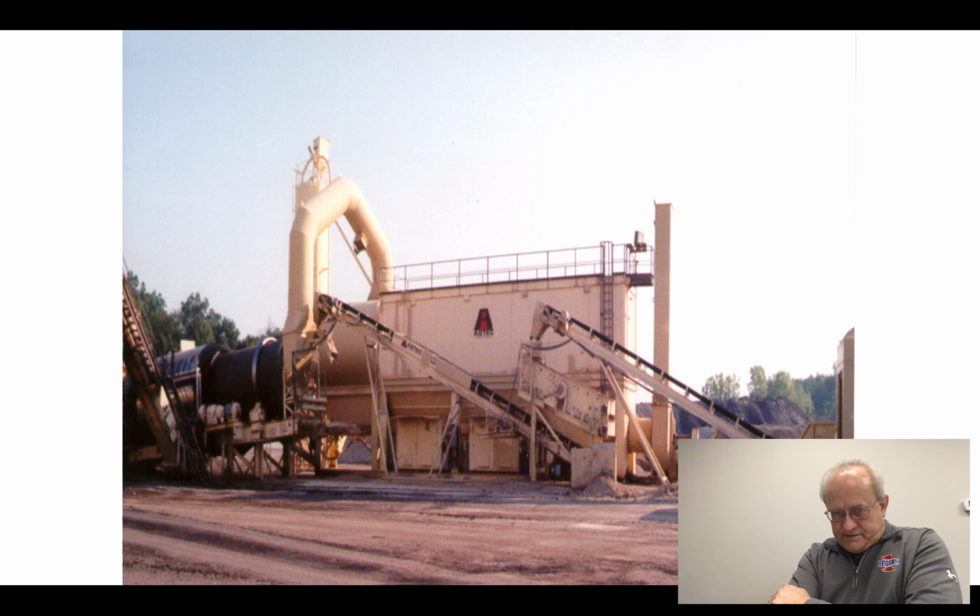Now, right behind the conveyors there is the bag house. So you take this 200, 400 ton an hour aggregate going through this drum and you're heating it up, major airstream. You're creating a lot of dust. Now you can't put this dust into the air. The bag house is nothing other than a huge self-cleaning air filter. The exhaust fan pulls the air through, is putting clean air out the stack. Those stacks have to actually be tested once every 5 years, in some instances more than that.